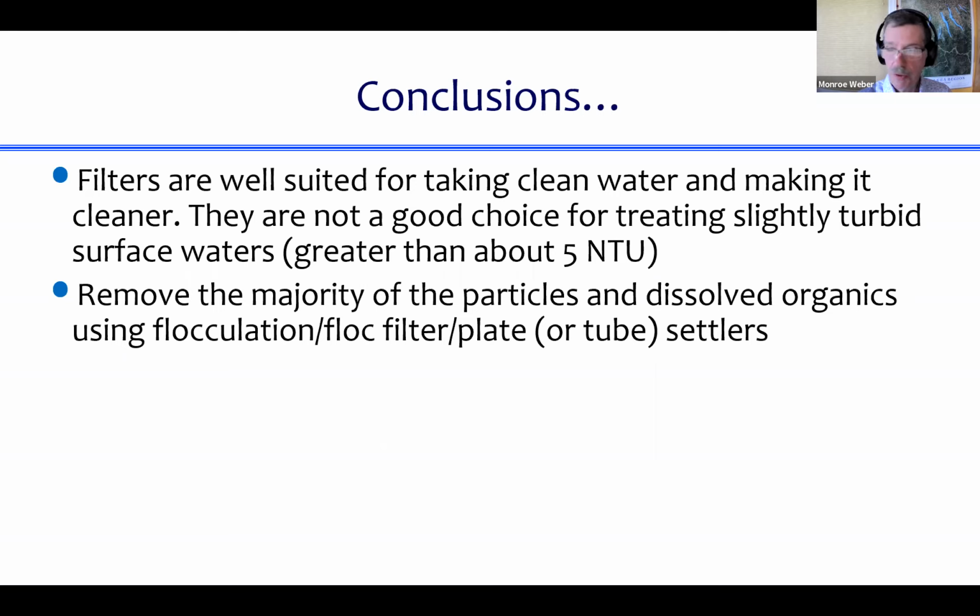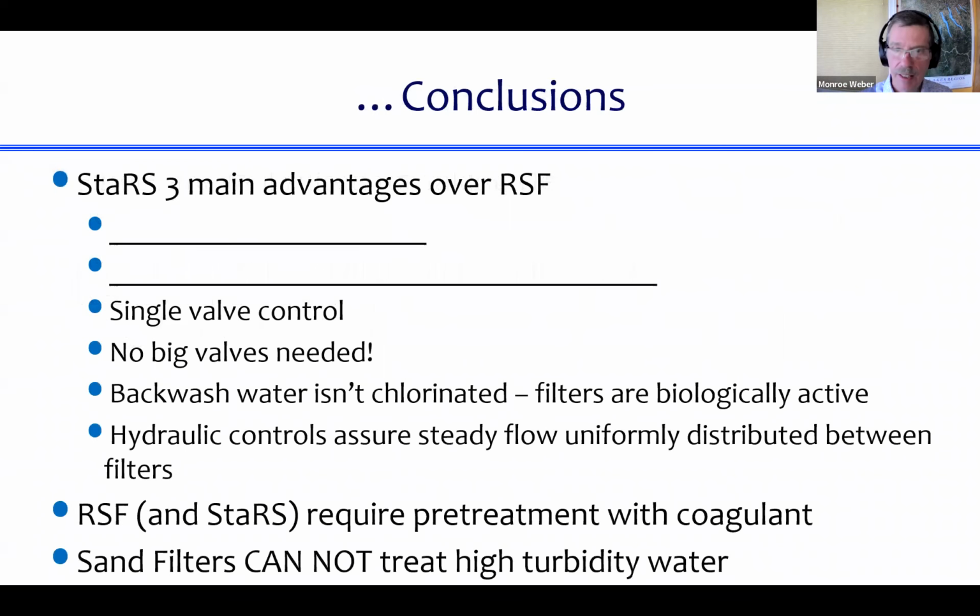They do remove particles and dissolved organics. The goal is to remove most of the particles and the dissolved organics using flocculation, flock filter, and plate settlers, and then you polish it off with the filter. Filter is the last thing you do after the water is already clean.